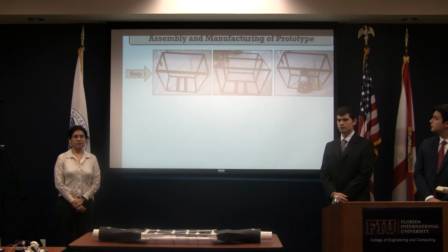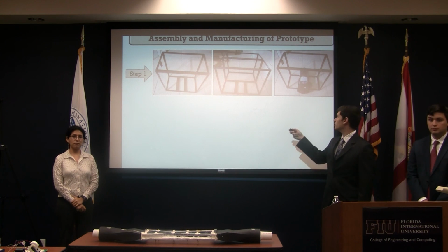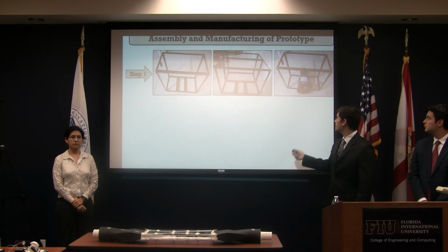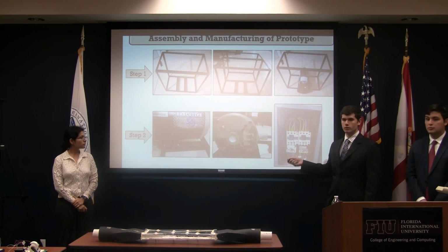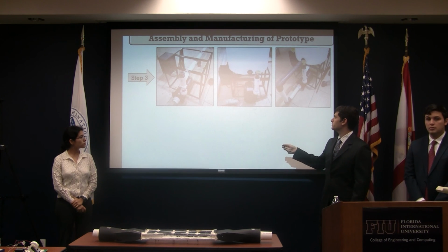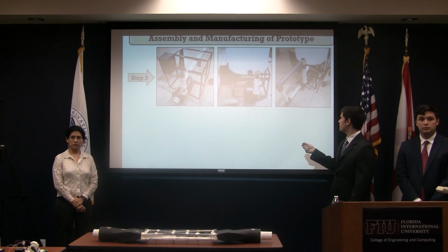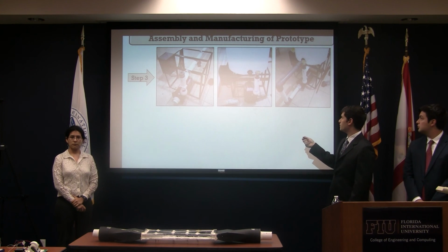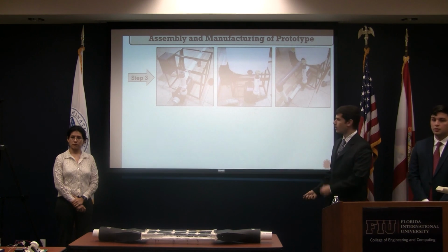So our manufacturing was divided in 6 steps. The first step was actually welding the frame, putting the 2 pieces together, providing a middle support for the tank, then securing the pump with the hex bolts and making the electrical connections for it, just as you would with a standard household AC system. Then we proceeded to gluing the piping system, the suction side and delivery side of the pump. This will be the delivery side of the pump, and this will be the suction side from 1 inch brought to 2 inch into the pump.